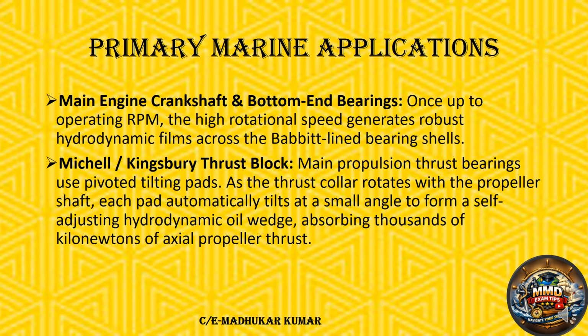So this thrust block lubrication is a separate topic basically, and I'm planning to do that. I'm going to make a clear understanding and explanation of the thrust block lubrication also. So basically, the thrust bearing has tilting pads, and they tilt in such a way that the separation between the contact surfaces happens, and the lube oil comes in between, and the sufficient thrust and pressure which is being generated by the propeller shaft is being absorbed by that. So this is a very interesting topic. I will discuss it later on.